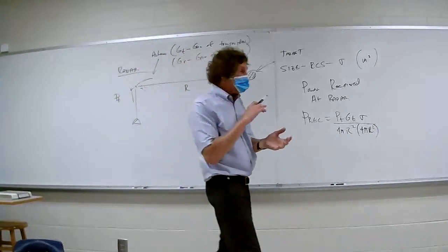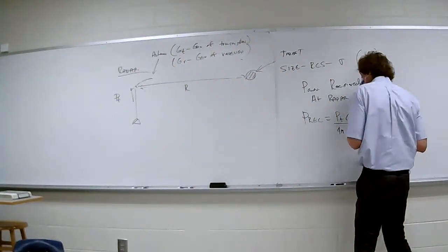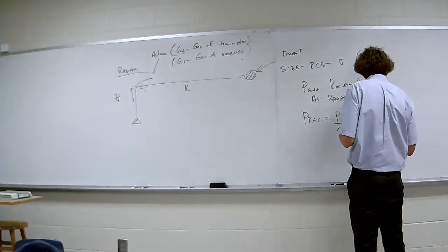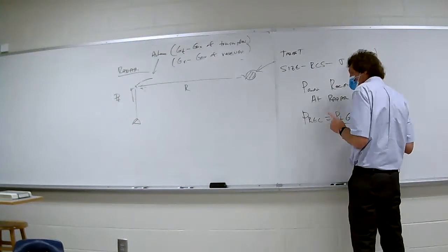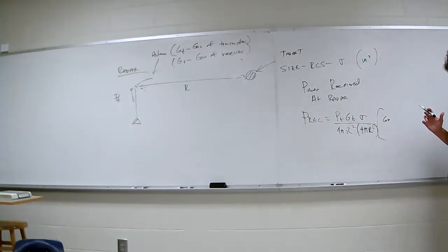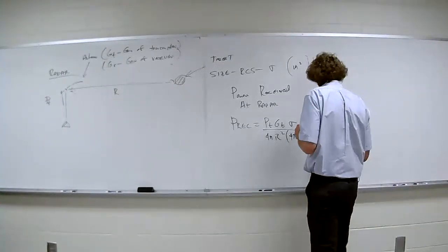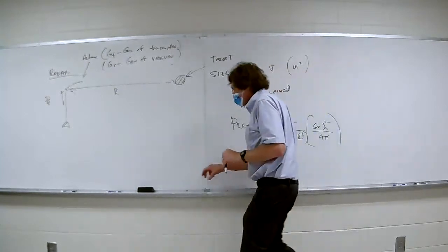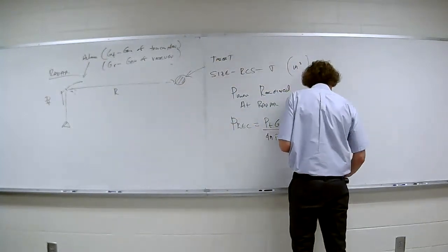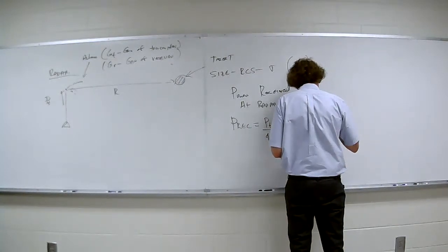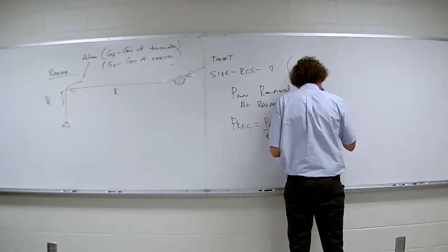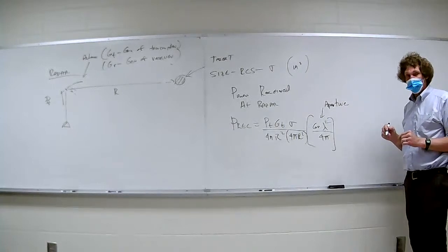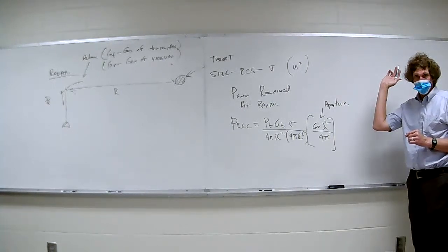Well, the aperture and gain are interrelated. Does anyone remember what aperture is in terms of gain? They're directly proportional, right? It'll be the gain of the receiving antenna, but there's one thing that enters in. Do you remember what it is? It's lambda squared, right, over 4 pi. And this, what I just put down, is the actual size, the area of the antenna, how physically big it is. It's the aperture of the antenna. Y'all with me? How many remember that? Or at least it's bringing you back.